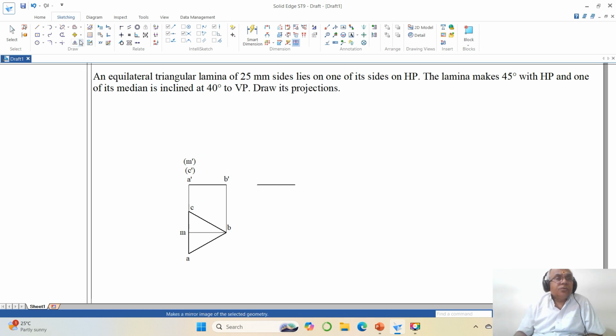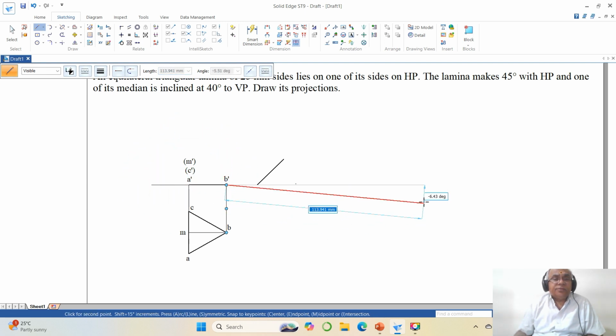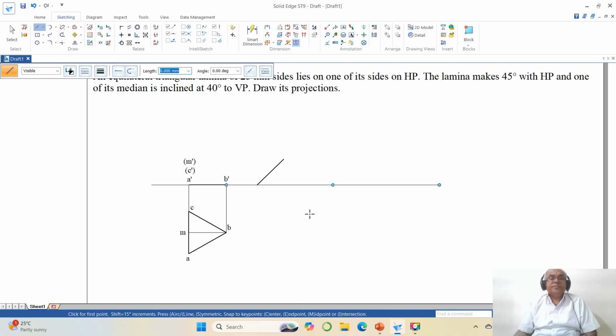Then go to zoom. Then go to rotate. Rotate, select this. You take end point of this to end point of this. So what is the rotation angle you want? I want this angle to be 45 degrees. Click here. Then you draw a line from end point of this in this direction. Similarly from here you draw a line from this direction.